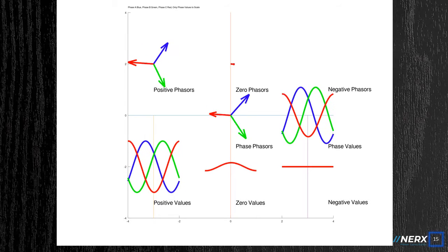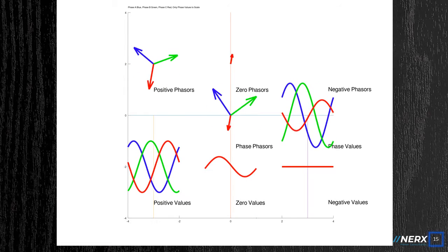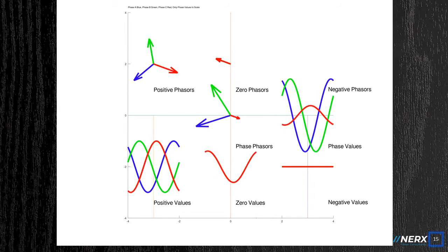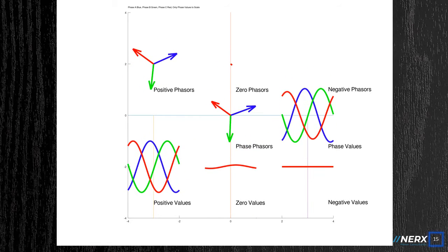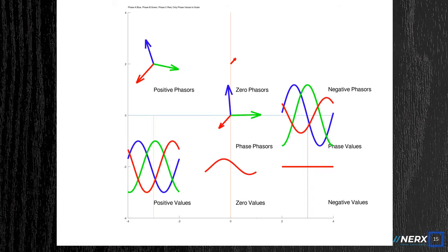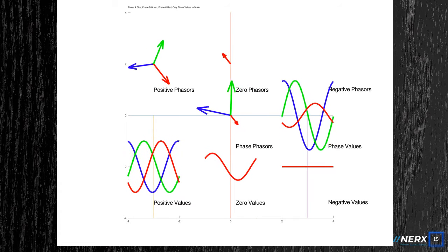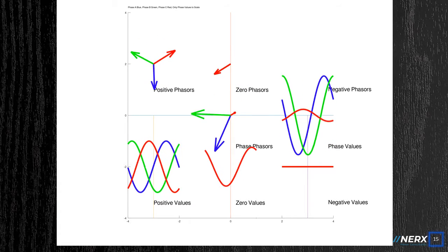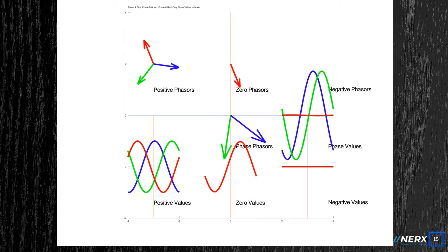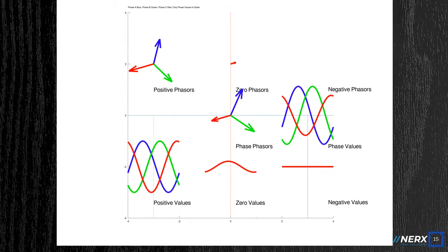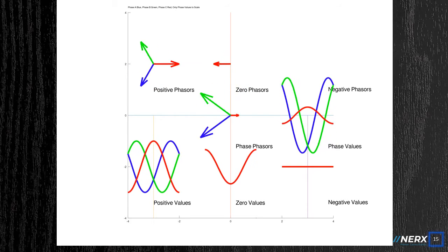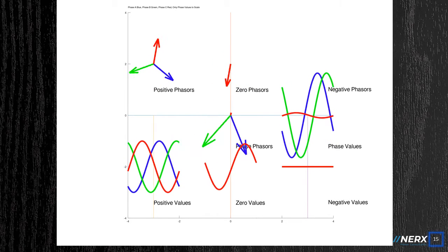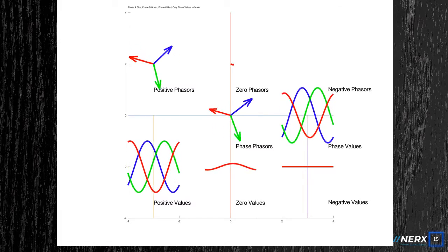Here are the voltage phasors you would see for a single line to ground fault on an impedance-grounded system with varying amounts of ground impedance. The amount of zero sequence voltage that develops is determined by how much the grounding impedance constrains the zero sequence or ground current. As the amount of zero sequence voltage develops, the faulted phase gets pulled closer to ground and the other two unfaulted phases increase in voltage to ground up to a square root of 3 of their phase to neutral magnitude.